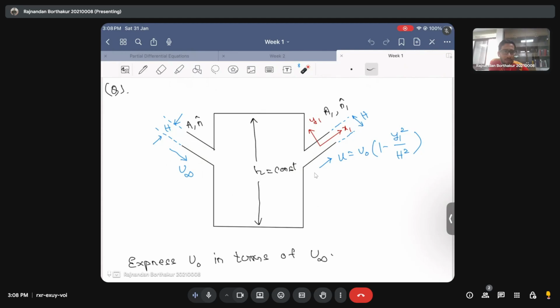The earlier problem had a varying water head, where the height of the control volume was changing with time, and the objective was to evaluate the rate of change of h with respect to t, or how h varies as a function of time. But here it's the other way around: the question says the head is now kept constant.